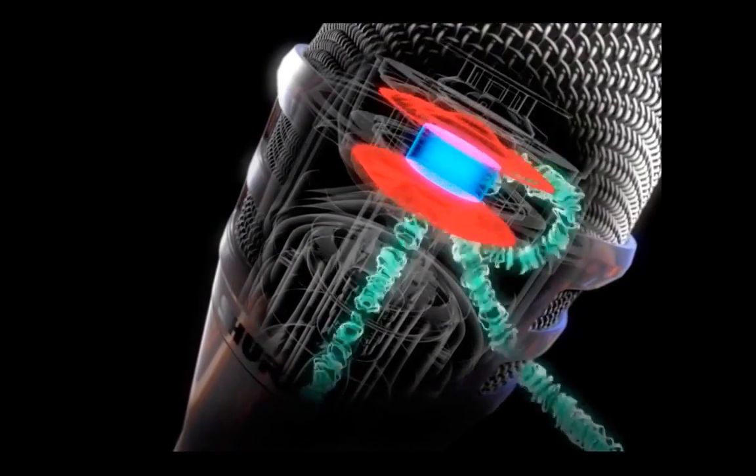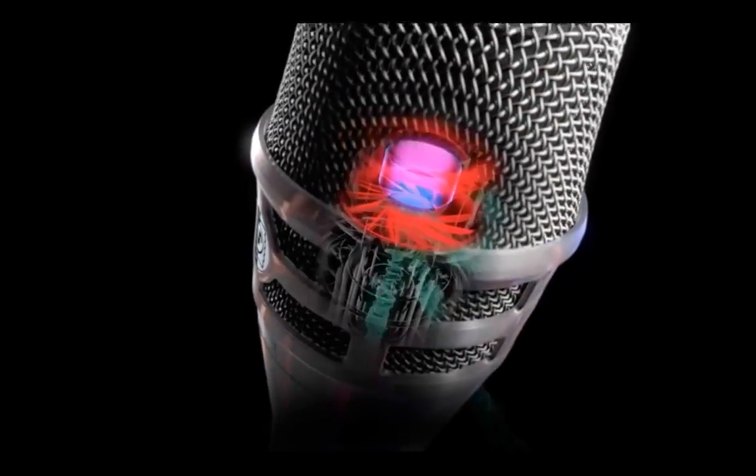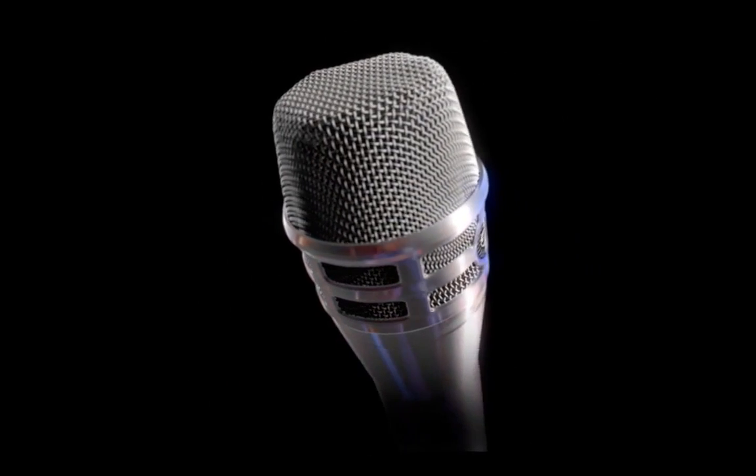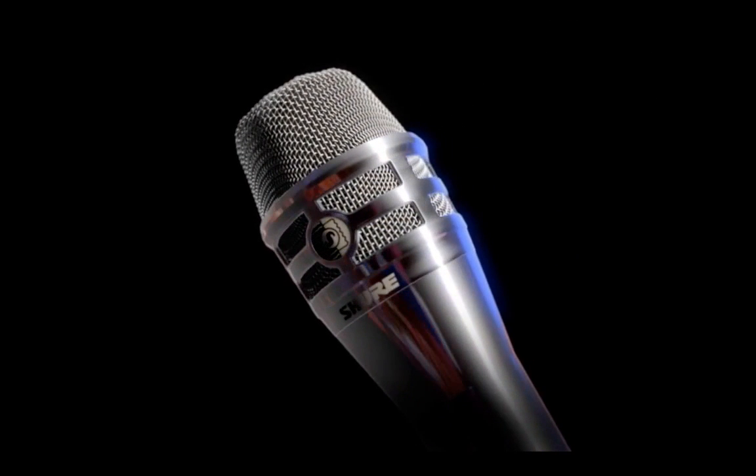And that reversed airflow is what we patented, and the presence of that second diaphragm in that network, at high frequencies, that diaphragm doesn't even exist. Sound passes through it. But at low frequencies, that's where it starts partially blocking low frequencies from building up as you start getting closer to the microphone. So it does it just enough to notice it, and it works really well. So we're pretty excited to finally share this new technology with you guys.